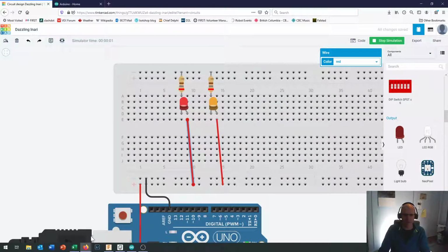Did you see the little USB cable plug into your Arduino right there? When you plug the USB cable into the Arduino, your computer supplies 5 volts over USB to your Arduino, and the Arduino turns on. And it provides 5 volts into the board right here, comes through this wire, and turns your LED on. That's not too fancy, but hey, it's working.